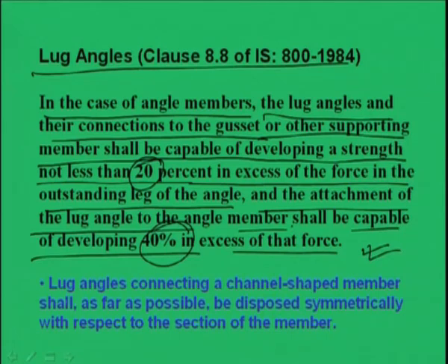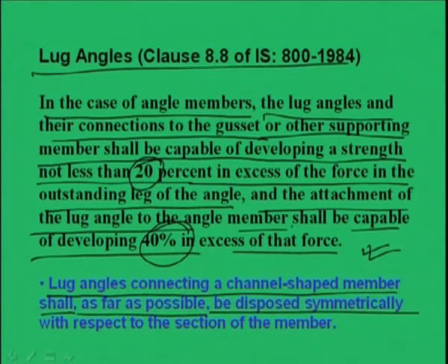Another thing is, lug angles connecting a channel shaped member shall as far as possible be disposed symmetrically with respect to the section of the member. This is important.